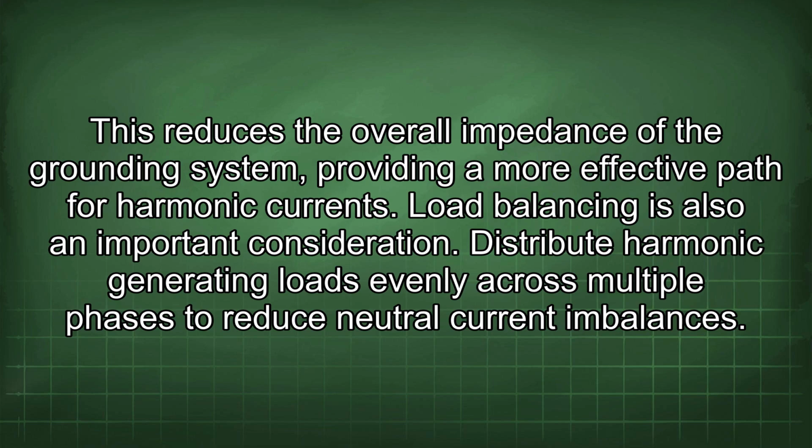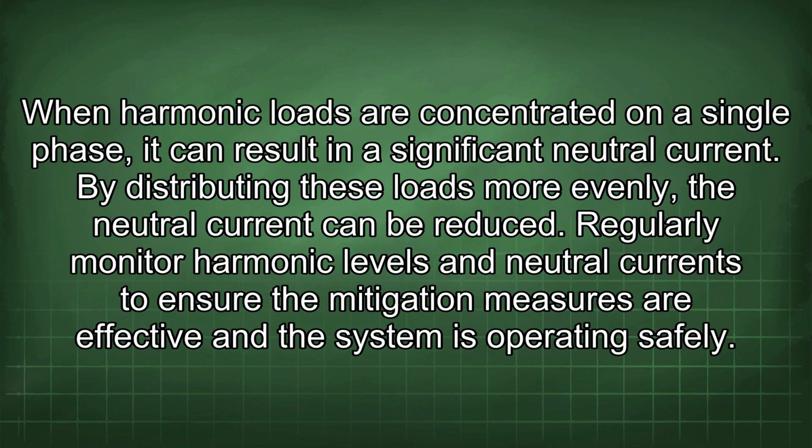Load balancing is also an important consideration. Distribute harmonic generating loads evenly across multiple phases to reduce neutral current imbalances. When harmonic loads are concentrated on a single phase, it can result in a significant neutral current. By distributing these loads more evenly, the neutral current can be reduced.